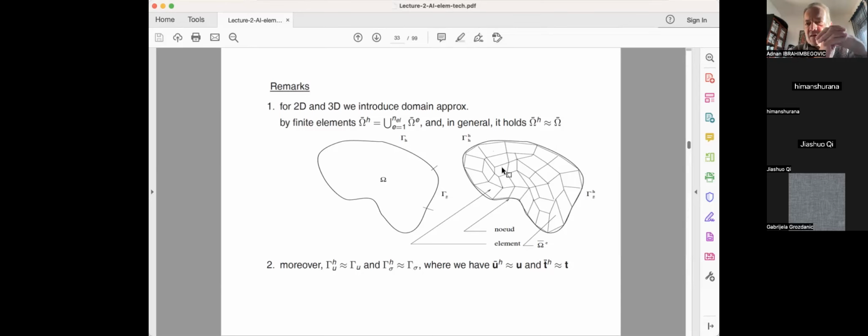Nowadays, I've seen a lot of development in isogeometric elements, and people use NURBS to represent this domain very nicely. But again, NURBS are no longer using polynomials, and the best approximation property with polynomials, or partition of unity type of guarantee and things like that, are no longer guaranteed. So you can have a very good solution for a special problem, but you can also have surprises for some other problems. And one has to worry about that as well.